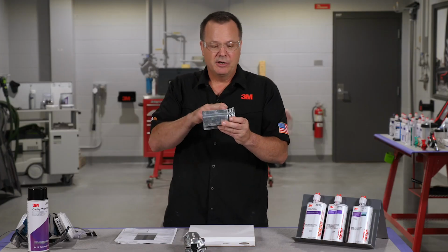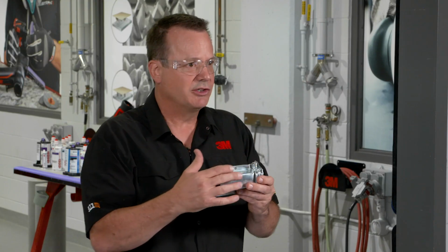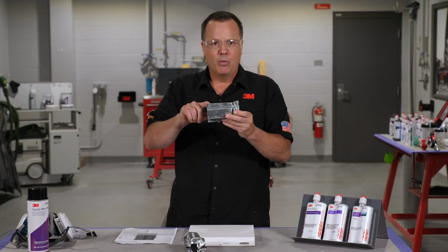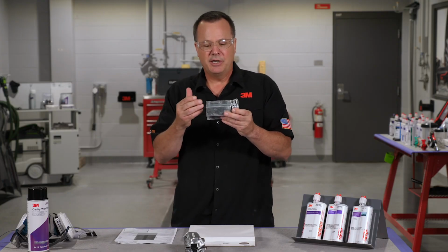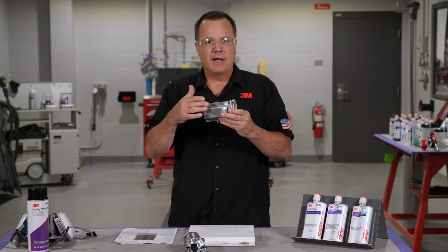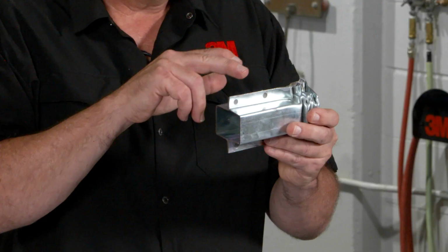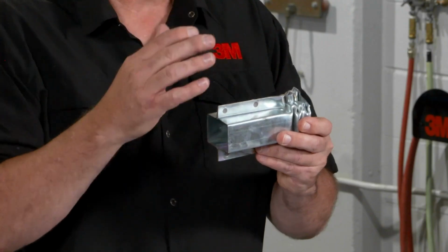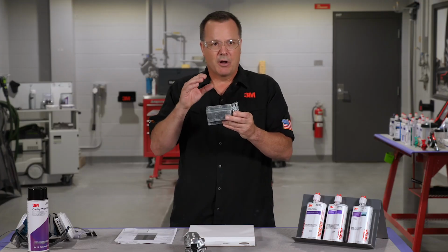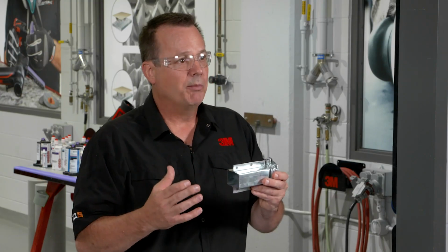Another benefit is you've got a continuous bond, not just a spot here and a spot there, it's continuous, so you get really good lap shear strength. The weld in there prevents the adhesive from ever going into peel mode and starting to peel. That's kind of the weakness of any adhesive is peel mode, and having that weld in those areas will prevent that from happening. So a lot of benefits to combining the welds and the adhesive together in weld bonding.